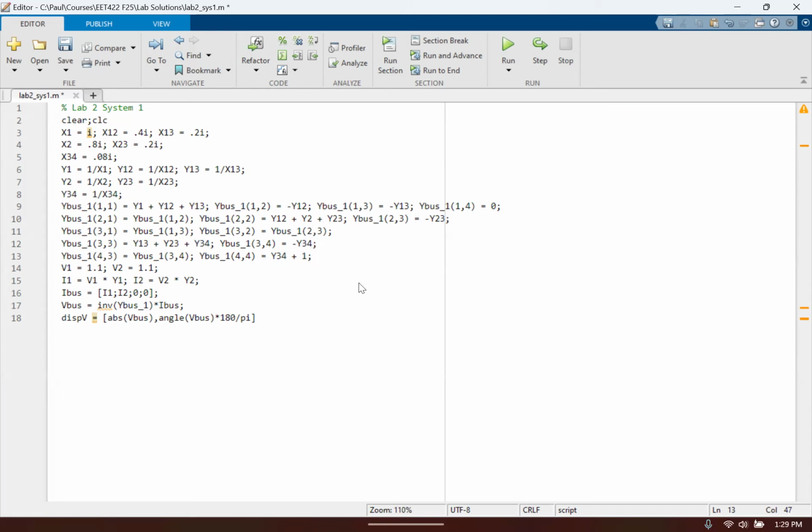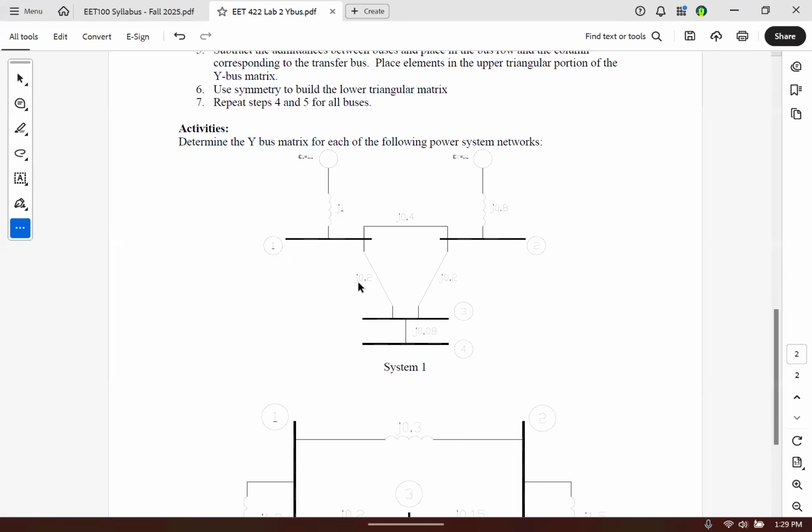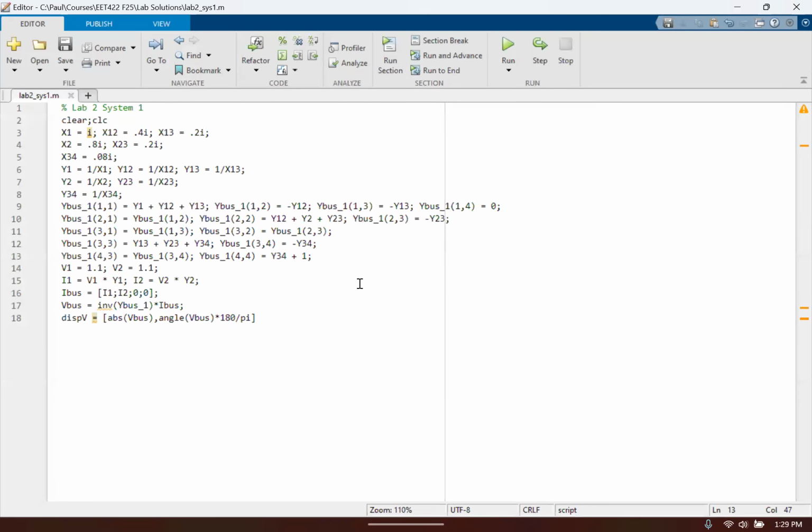So when I invert it, it's still 1 ohm, and we're just adding it. So essentially all I did was put a load here, correct? I'm not going to put it in between two buses because that's just another impedance between the two. I'm actually going to stick a 1 ohm resistor in here. So that's equal to R, and 1 over R, which is equal to Y, is still 1, isn't it? So let's run that.